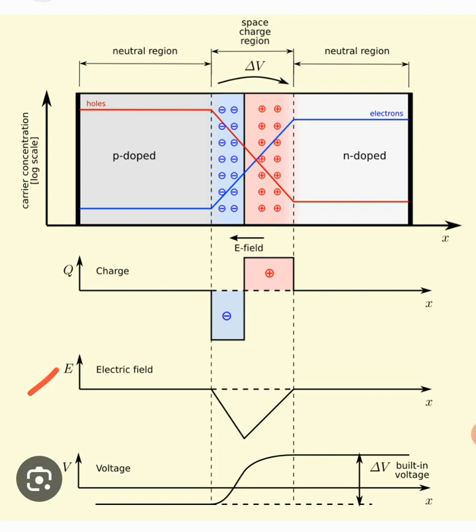Similarly, the electric field starts from the P type material, and at the junction it is the negative maximum. In the depletion region with the negative ions in the blue it is increasing negatively, and then toward the red region where positive ions are, it is increasing towards zero.